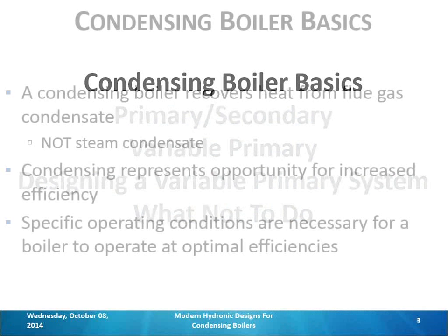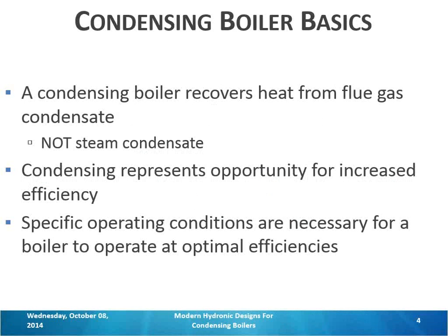For natural gas-fired equipment, that would be anywhere above 88% roughly. But we need the right conditions to get this efficiency. So if you take this condensing boiler that's marketed at, say, 96% thermal efficiency, and it's put in a retrofit application with the same control strategy and the same water temperatures that were used with that old cast iron boiler, are you going to see that 96% efficiency? No, definitely not. So you need the right conditions to get there.